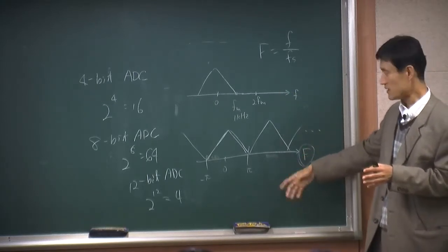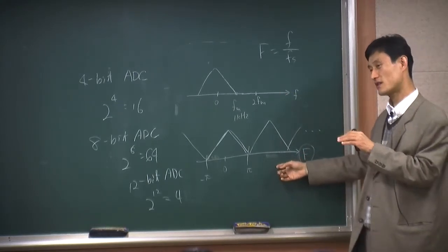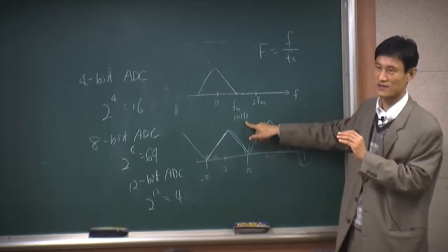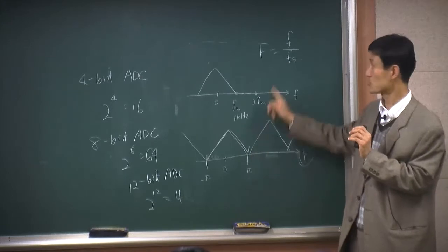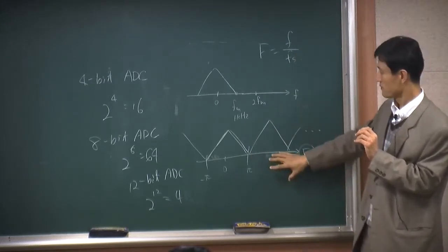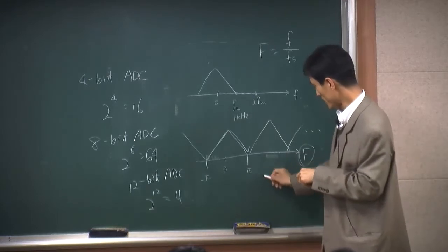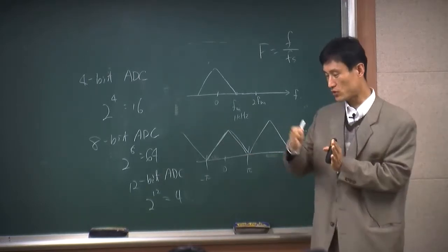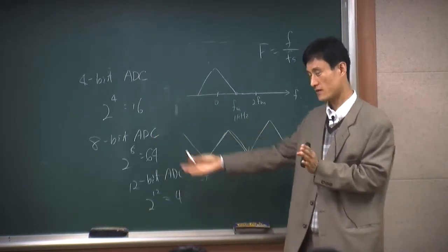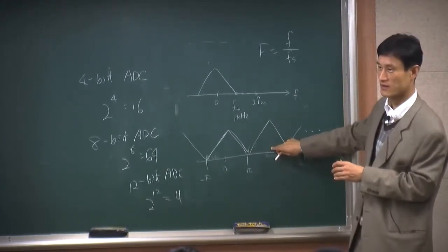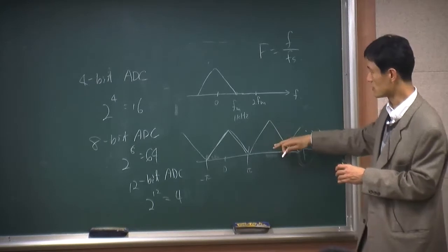Okay? In this case, this is the digital frequency. So based on this, there's nothing like hertz. We don't use hertz because we are doing normalization. Okay? So you're always going to see this one. And then what happens is this repeats. Every 2 pi, you repeat. So this is what happened at the digital signals once you sample it. Okay? Once you sample it, it's going to change it to this.